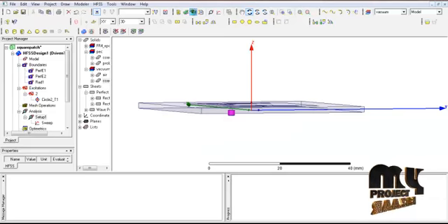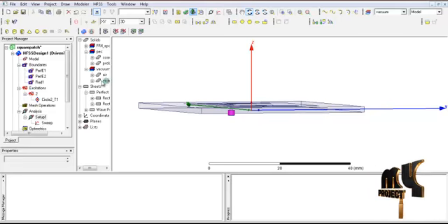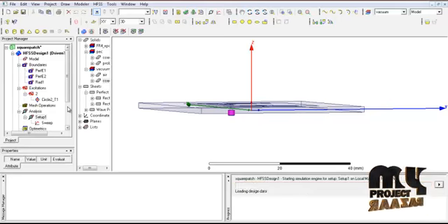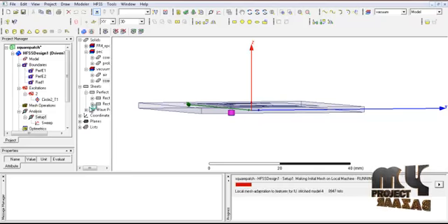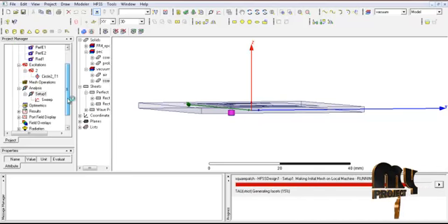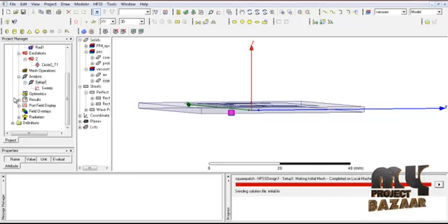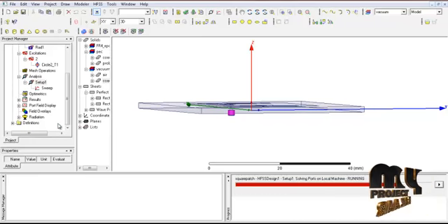So this is the run. Here we click this button to run the overall process. It takes some time to display the results. And then finally we calculate the overall results, like return loss, VSWR, and radiation pattern, like 2D and 3D of the process.